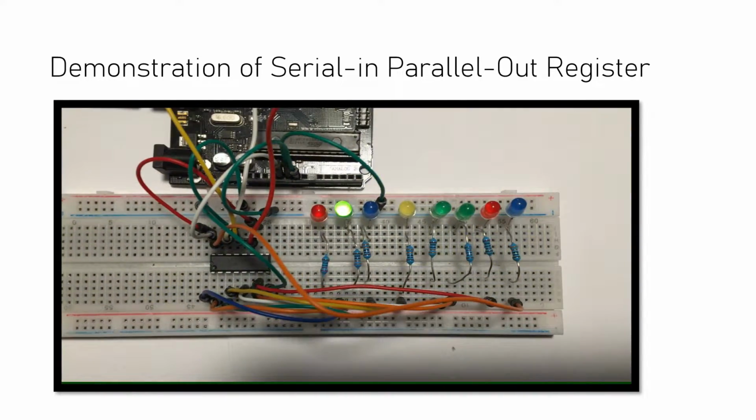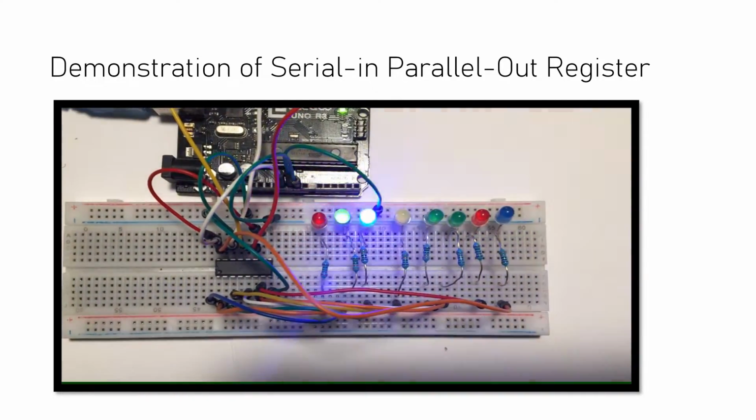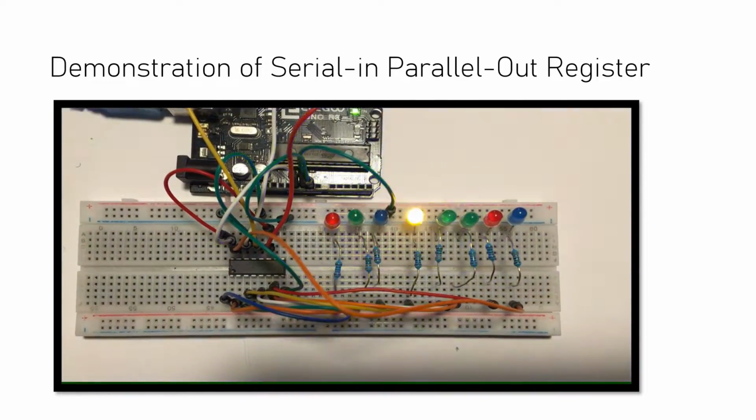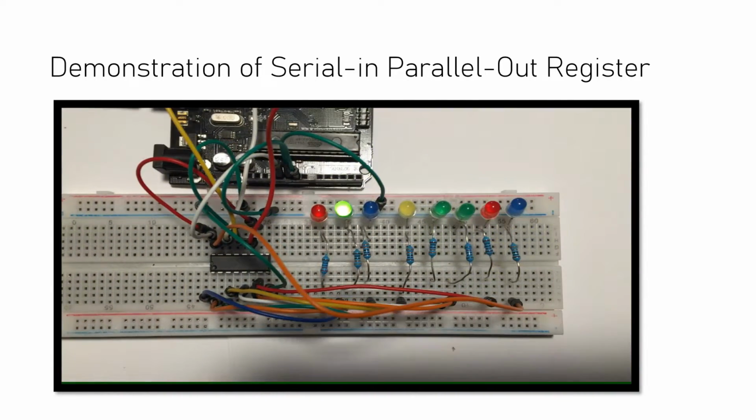Then we use this Arduino Uno to provide the data entry to the register. That is how we're able to get it to provide the data through the output pins, from Q0 to Q7, and then that value is shown through the LED display lights. This is the pattern of how the data is outputted from the register.